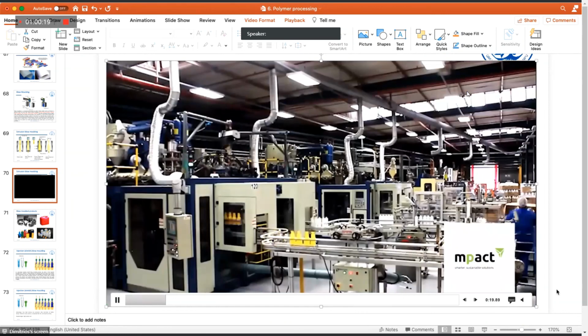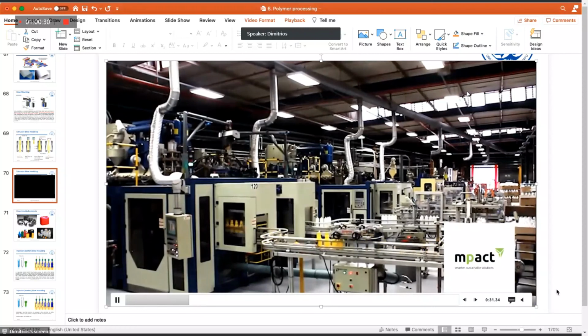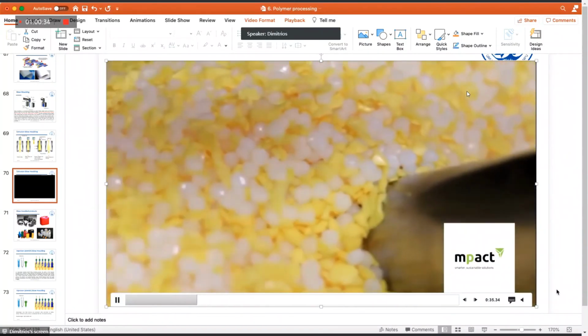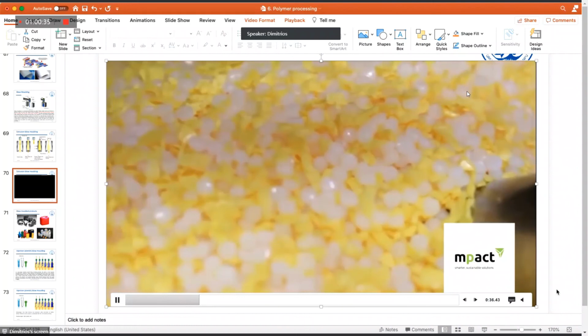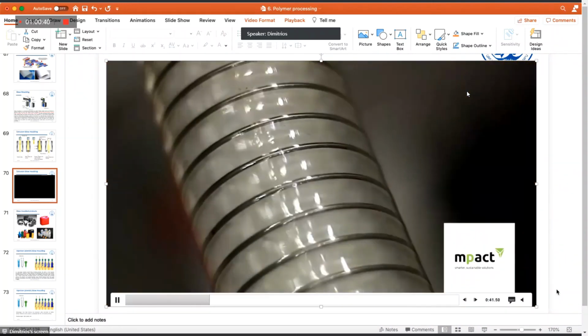This is the extruder. So you can see the extruder. Okay, this is the partition that I was telling you. It comes out from this specialized die, and we control the pressure and the temperature so that this material is soft, but it's not in a molten state.